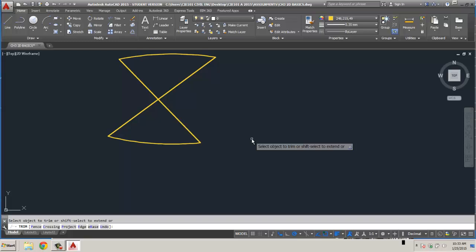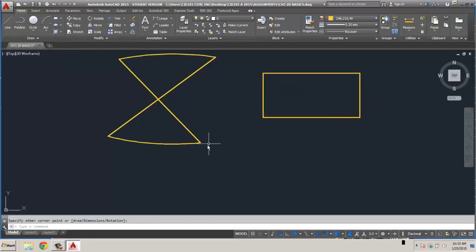So we've talked about circular arcs, elliptical arcs, rectangles. We've put those in. Let's see what else we've got. Rotation tools. This is under our modifications. So in other words, all our drawing tools are located right here. And let's put just a box out here. Our modification tools, I showed you the mirror, the move, copy. Not sure what the length of that box is. Let's just measure it. Point to point tells me this is 20.